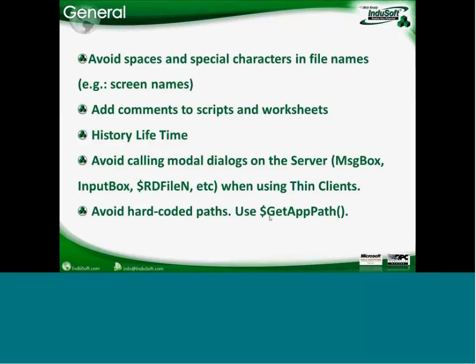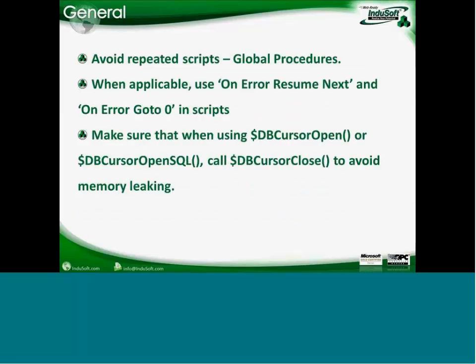Also, as much as possible, use relative paths, and you can use the getAppPath function from InduSoft to get the current path of the application. So if you move the application from one directory to the other, from one computer to the other, scripts and hyperlinks keep working. Avoid repeated scripts.